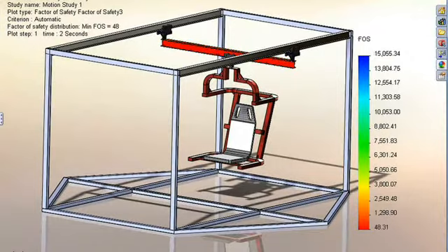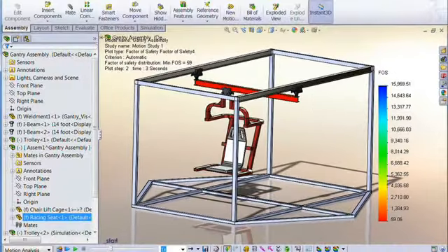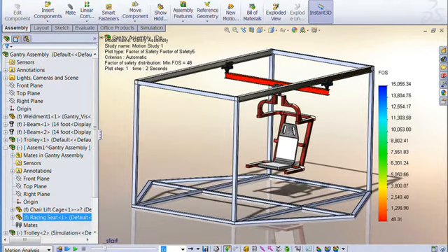I think we can see here that the factor of safety is maybe a tad high. It's telling you, as we thought before, we're majorly over strength. We've got a lot of weight in there that we can maybe take out, and a lot of cost we can take out of your design as well. You've got a lot of wiggle room, as I'd call it, in this design. You can actually really hone it and optimize it.